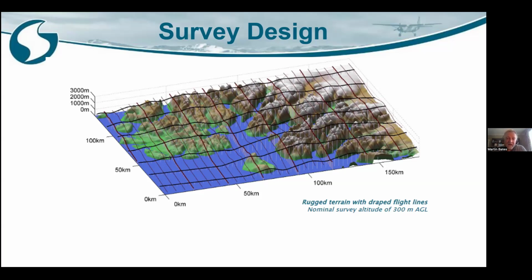And they can be helpful for gamma ray data because sometimes you have issues with conditions on the ground changing. It's quite common to fly long surveys. It might rain, the ground becomes wet. That reduces the gamma ray radiation, so you get lows in your data from some lines relative to other days. You can use a line that's flown perpendicular to them to help you figure out what's happened and correct for it. It's not an exact science, but it's very useful, and we've leveraged that in the past for gamma ray as well.